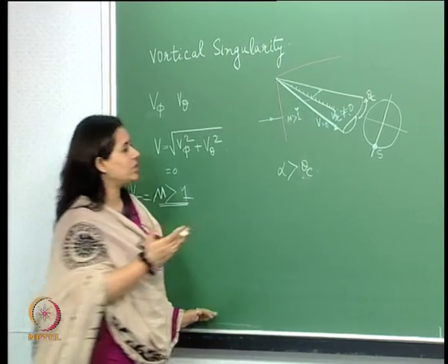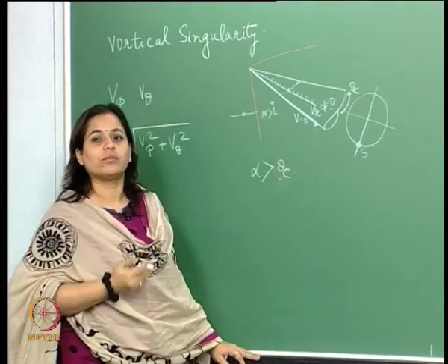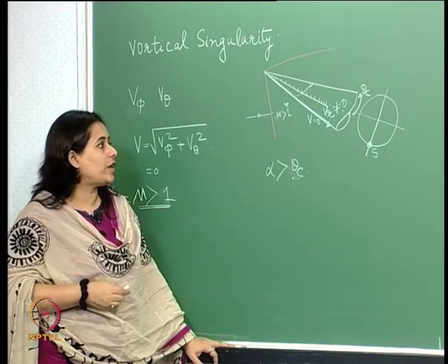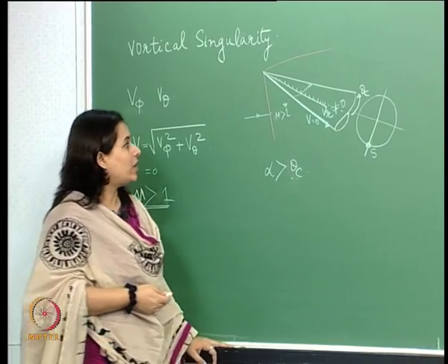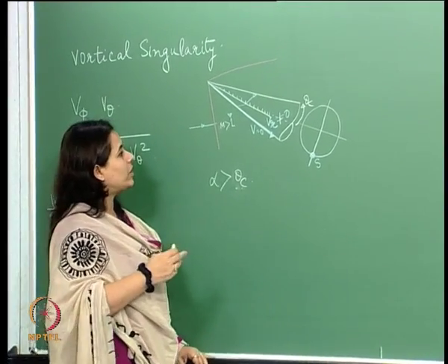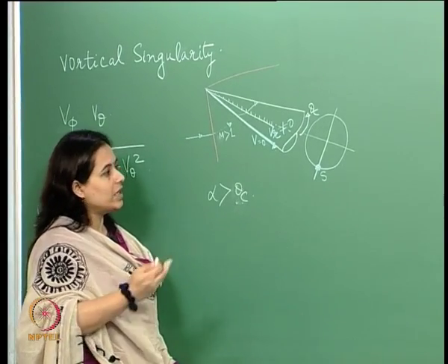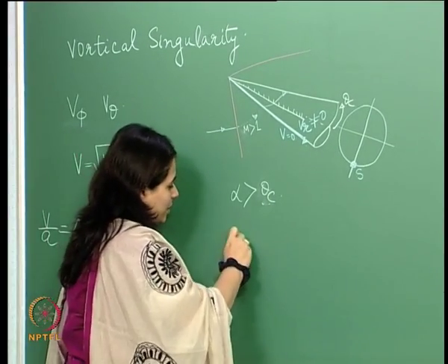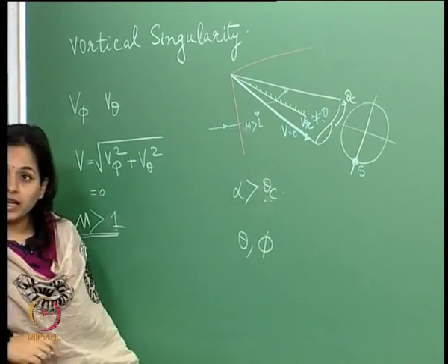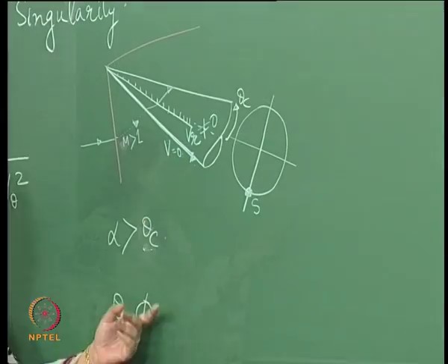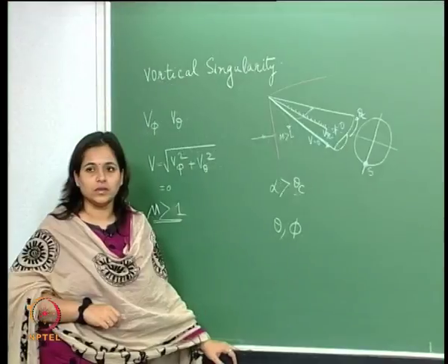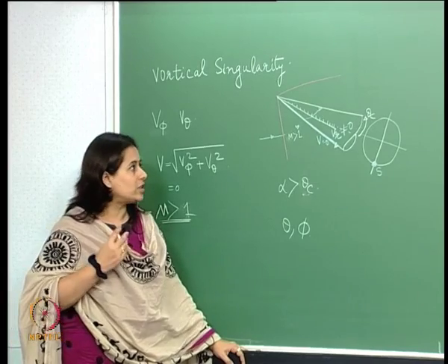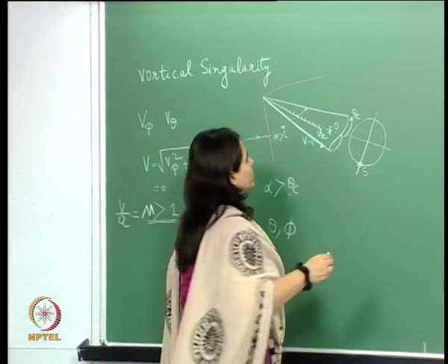You could have this projection as an ellipse for that matter. And in that particular case, if I do have an ellipse of that sort, even for an axisymmetric case, when we have an elliptical projection of the cone, there will be two independent variables. There will be theta and there will be phi. Unlike a right circular cone, where del phi doesn't matter, or v phi is 0 for an axisymmetric case.